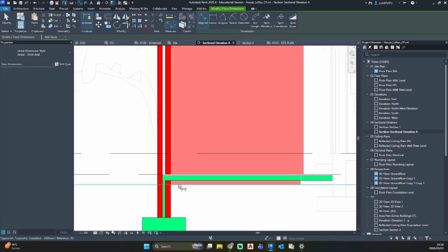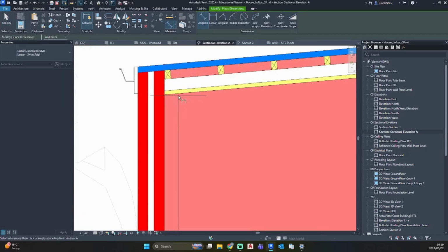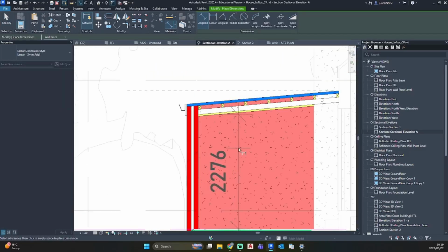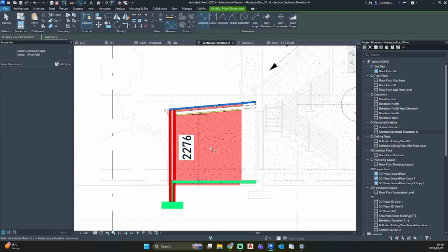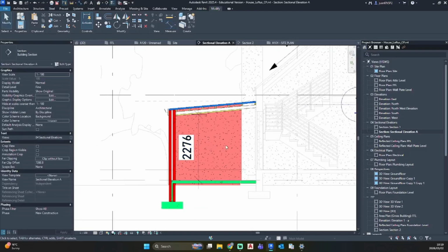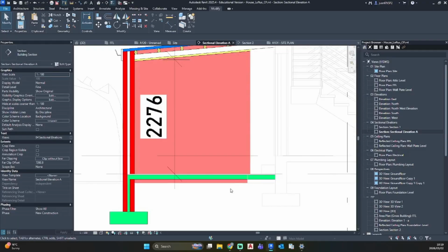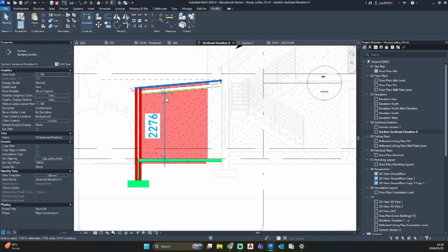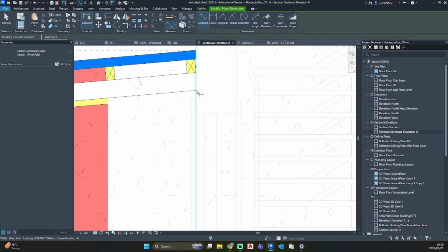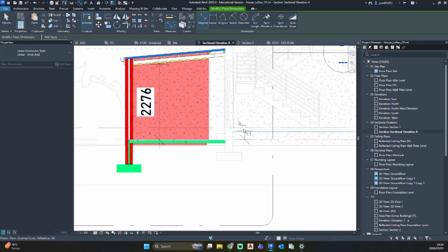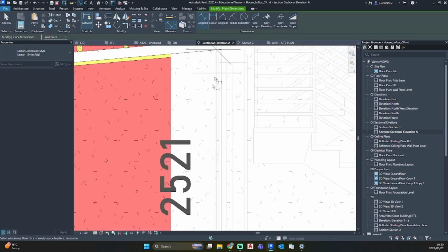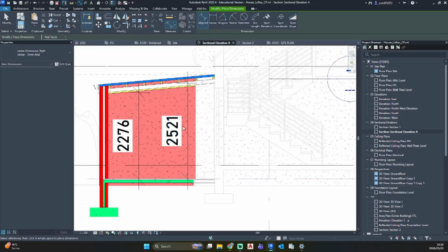And now to check if we comply with something under part C, we have a 2.2 meter height on this. With that, 2.1 meters is the minimum, but we can check top as well so that we can do a click there, 2.5.